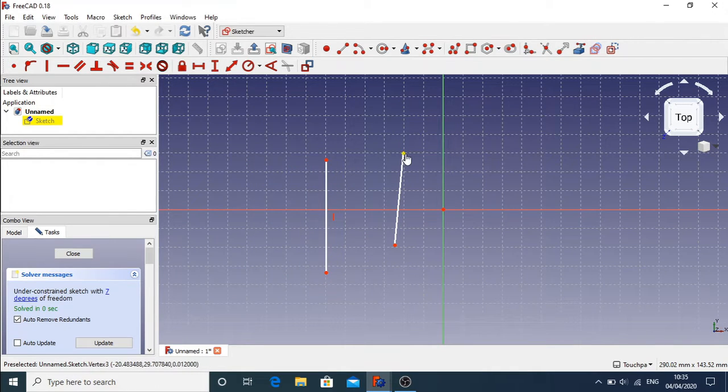The next one we do, this side, is put a horizontal constraint on. These are the easy ones. So the same as vertical, but it's constrained against the horizontal. So no rotation. We can stretch and unstretch this line as much as we want, but we will not stray from the horizontal axis. So to get rid of these constraints, just click on them and delete.